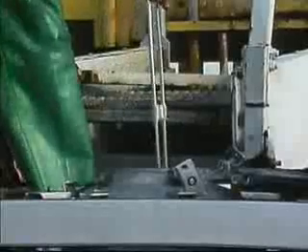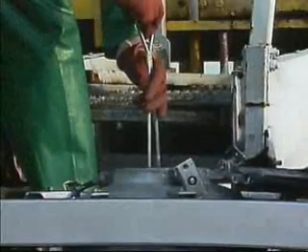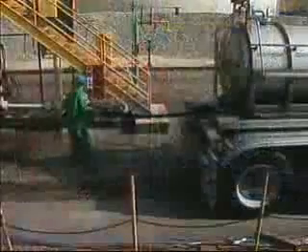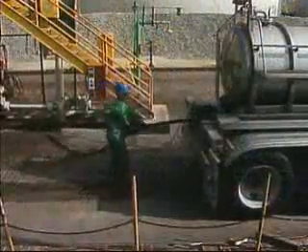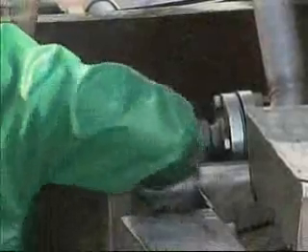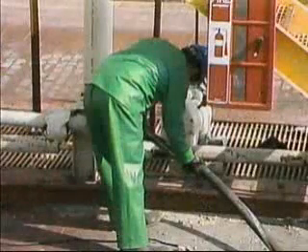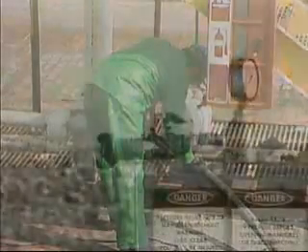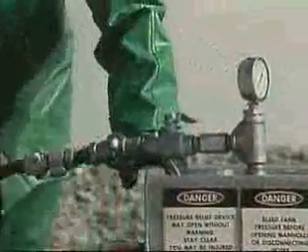After the operator completes the inspection, he samples the contents of the tank. Then he prepares to make the required connections. He starts by attaching an unloading hose that connects the truck's product outlet with the line leading to the appropriate storage tank. Then he connects the air hose to a vapor line at the top of the truck.